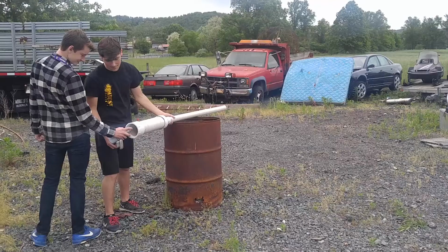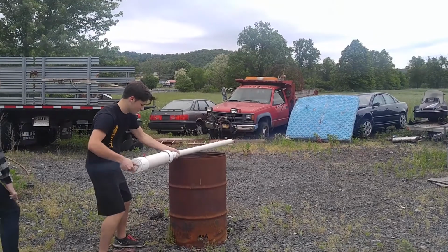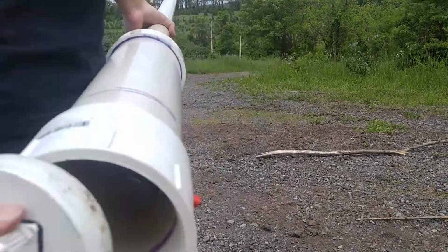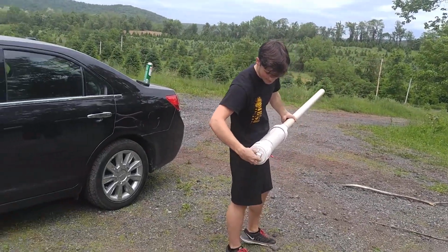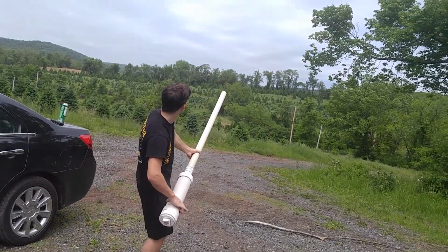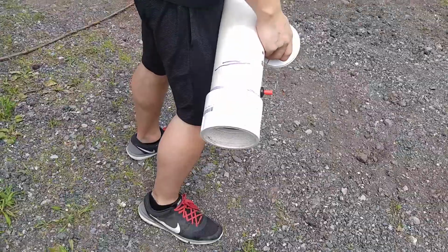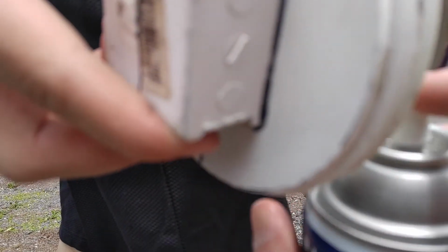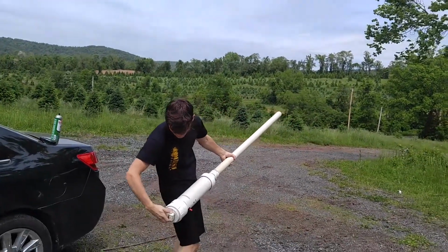Although the cross-sectional area of the projectile is relatively small, drag should still be accounted for if you're trying to make an accurate calculation. The accuracy of the level used to level the 55-gallon drum is another possible error, which may have inadvertently introduced some unwanted velocity components on the Y or Z axis. Along with the accuracy of the level, another variable is whether or not the cannon was held flat relative to the top of the drum, which, since we did not have a mounting device, is a possibility.